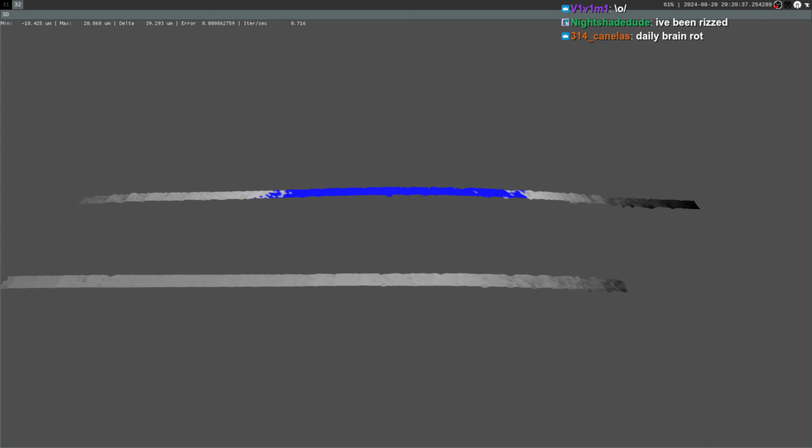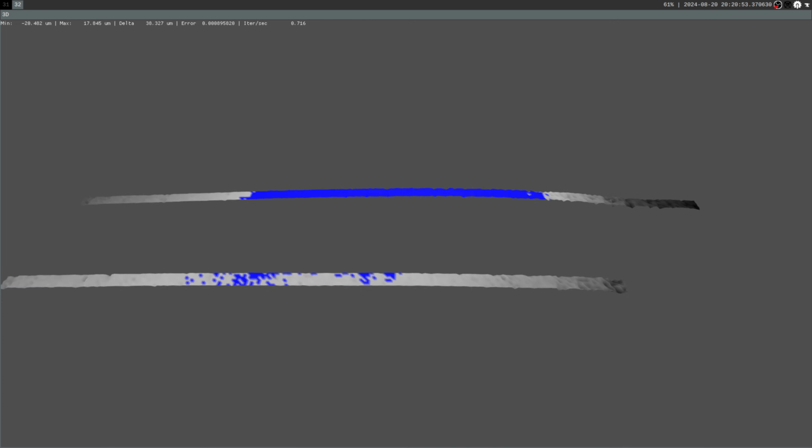It's pretty hard to measure. I don't have a straight edge or a parallel that is as long as the lathe. So I have to basically try to approximate where things actually are on the lathe through the magical process of hinging a smaller piece of straight edge on the lathe beds and trying to take measurements from that.